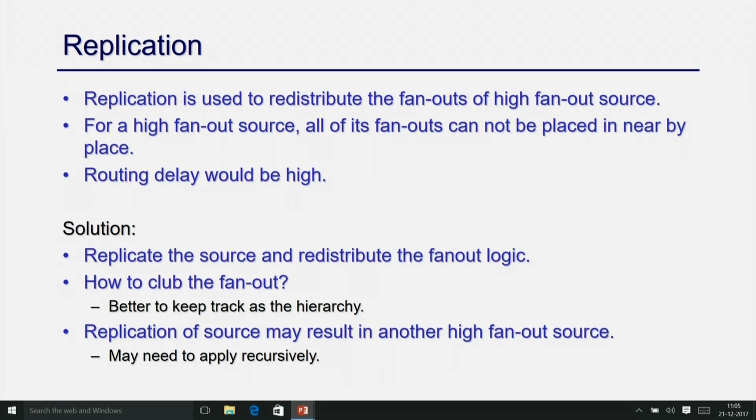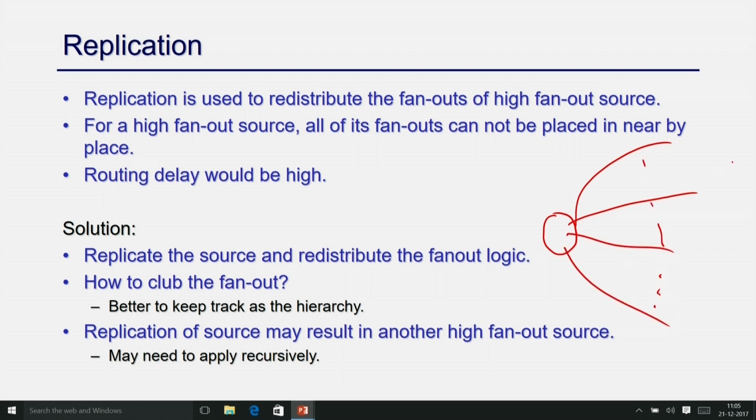Okay. And what is this? If you just think about a high fan out node, right. Suppose from this node there are 1000 fan outs. It is very common in design, right. When you go to the logic level, when you have all these gate levels, there may be some sources like clocks and so on, which actually have very high fan out, things like reset pins and other pins, which generate very high fan outs, right, 10,000 fan outs.